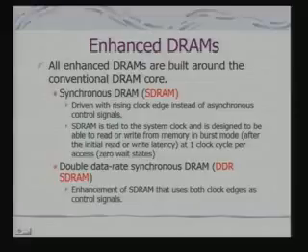So you do not need what are called wait states. Because RAS and CAS are asynchronous signals generated by the memory controller, the time taken to get the data would be more than the bus clock, the clock at which the system operates. So the system would need to wait to get the data from the DRAM, and that's why wait states get inserted. But if these RAMs can be synchronized with the bus clock or the system clock, then the wait state requirement can be eliminated, and that is the basic motivation of designing the synchronous DRAM.